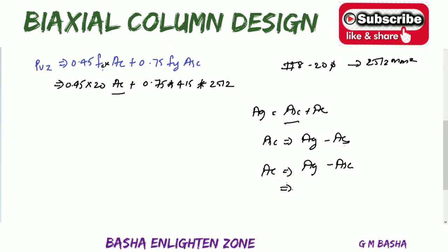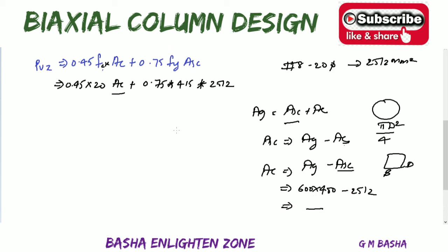So what is your gross cross sectional area? Your gross cross sectional area will be equal to 600 by 400 or 400 by 600 square. But if we are solving for a circular one, that will be equal to pi d square by 4. Here it will be rectangular, therefore b by d minus, what about area of the steel, which is 2512. If you simplify, you will get area of the concrete value directly, and whatever the value obtained here, you please substitute